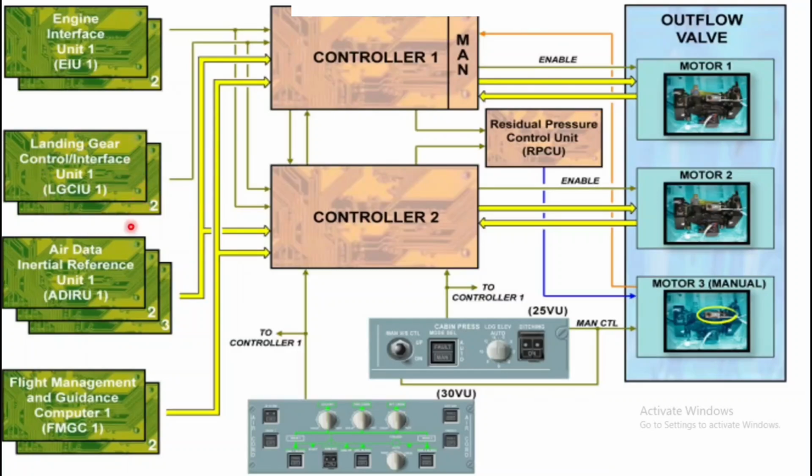So all three are taken care of by this. Just for example, the aircraft is on the landing gear and the aircraft speed is whatever required speed, it will start going into pre-pressurization mode. Once it goes to 15,000 feet, it will go into complete automatic mode for pressurization, and after landing it will go through the depressurization sequence. So this is a function of the ground-flight logic.